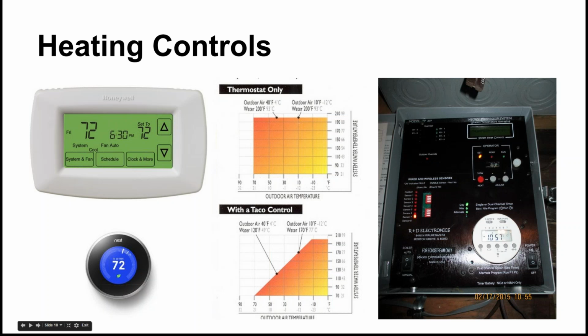For hot water boilers, one thing you can do is make sure that the temperature of the hot water boiler is the optimum based on the outdoor temperature. So basically, if the outdoor temperature is higher, like it's maybe 40 degrees out, it's not super cold, but you still need to be heating your building, the water temperature will be maybe at like 120 degrees, when the maximum it can be is 170.